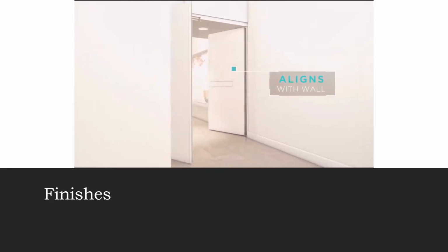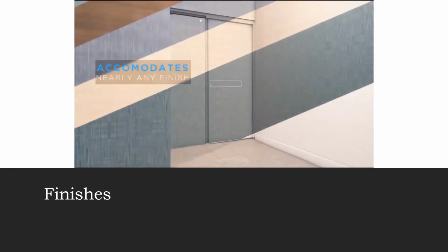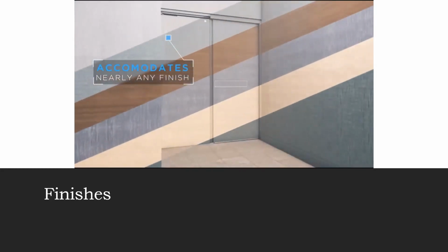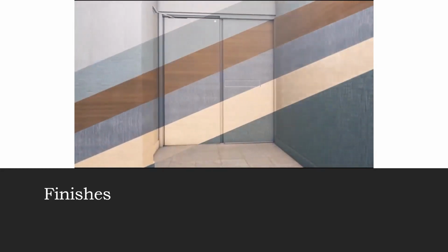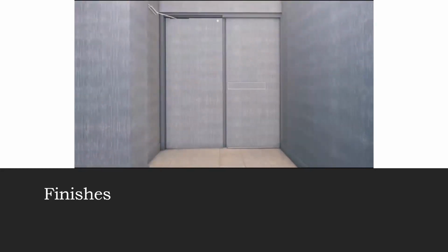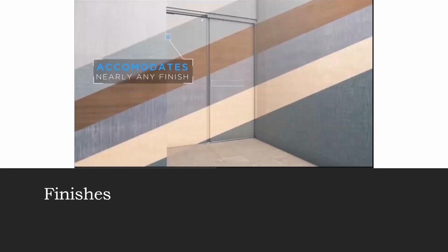True wood veneer, architectural metals, architectural films or overlays, wall coverings, paint, primed. The only thing you can do in the field is paint the doors. Other than that, the manufacturer will have a certificate of compliance allowing them to put the finish on the door at the factory.